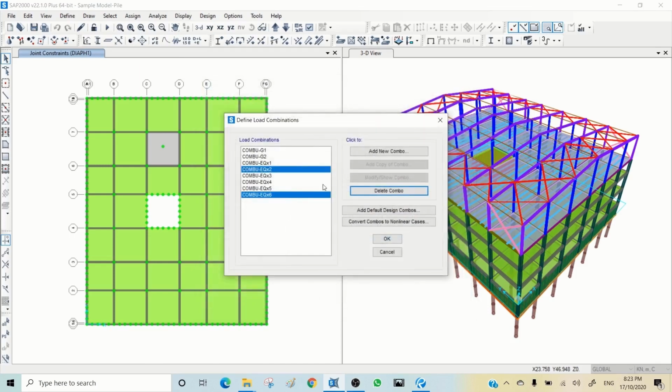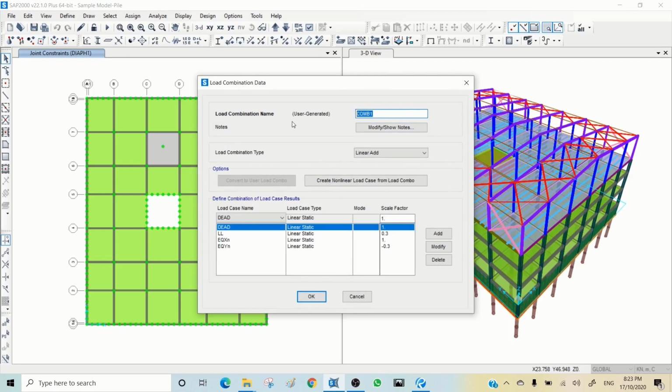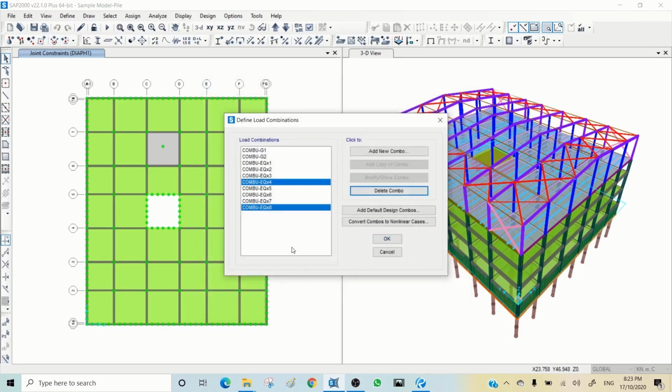And you can see when you press OK, you see which load combination is the source of the new one you created. And this is the last one. Add a copy of combo and changing this one to 8, and change this one to -1. Modify. So you see we have just 8 combinations, skipping another 8 combinations for earthquake, for eccentricity. So as I said, you can just have the 30% with no eccentricity and use it, or do this one, but it really goes back to your local standard. So this is for X. We need to do the same for Y, so I skip that one.